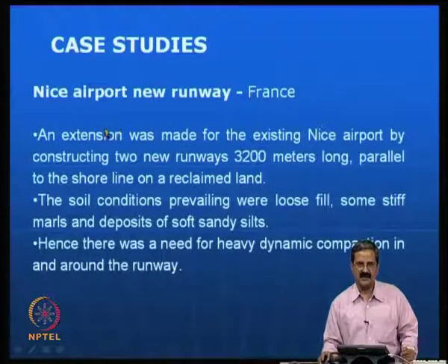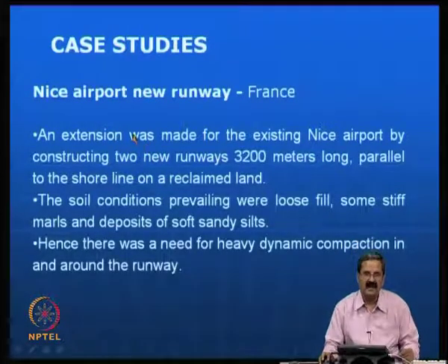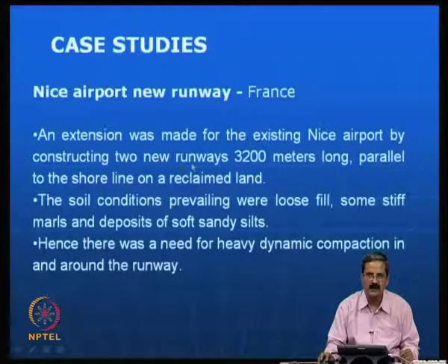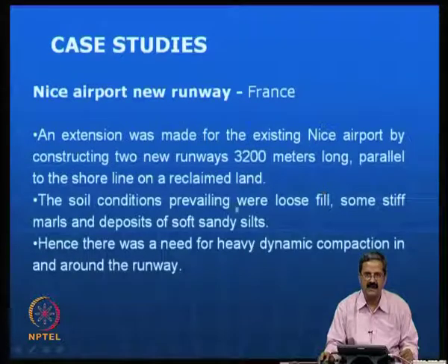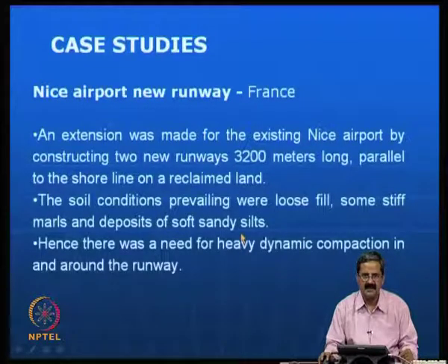You can see that this is a Nice airport runway, new runway. In this case, an extension was made for the existing Nice airport by constructing 2 new runways. The runway length is about 3.2 kilometers long, parallel to the shoreline on a reclaimed land. The reclaimed land has very low properties, the soil conditions were loose fill, some stiff marls and deposits of soft sandy soils, and hence there was a need for heavy dynamic compaction in and around, I mean close to the runway.